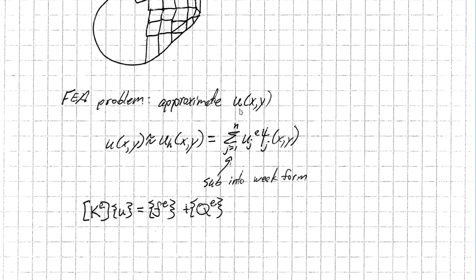So how do we solve for this scalar potential? As we did in the 1D case, we're going to approximate it with displacements over an element, and that element will have nodes 1 to N on it. So one example is here, you'd have 1, 2, 3, 4. So say a 4-node quadrilateral element.